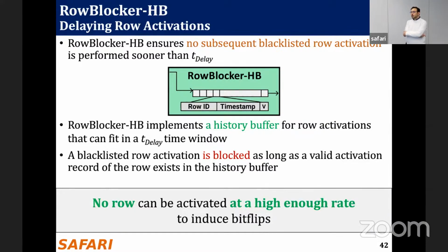The counting Bloom filter actually doesn't mandate a particular hash function. You can put whatever hash function you want over there. To make it low cost in terms of chip area overhead, we used these H3 class hash functions, which are basically just shift and XOR operations. As a result, we didn't minimize the false positive rate because of choosing these hash functions.